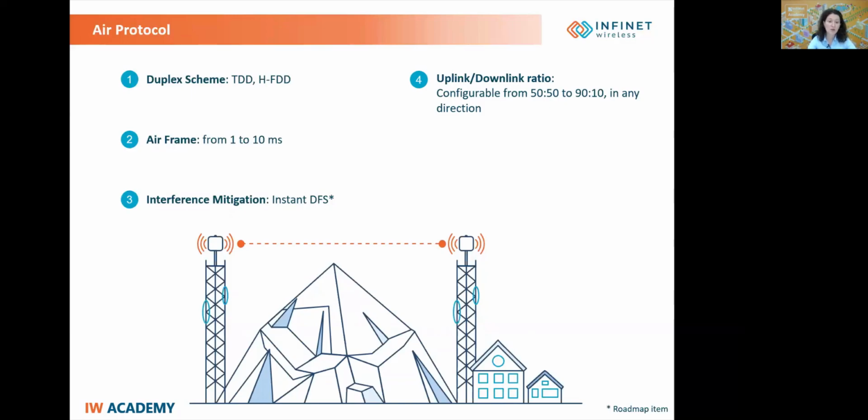This is particularly useful for asymmetric traffic demands, like in the case of a CCTV that requires full capacity in the uplink. As we discussed, when operating in highly interfered environments, Quanta 5 dynamically selects the most suitable modulation and coding scheme for each polarization and ensures the delivery of all transmitted packets using an advanced ARQ algorithm. The data transfer takes place seamlessly with the proper quality in any type of external conditions, from harsh environment interference or lack of visibility.